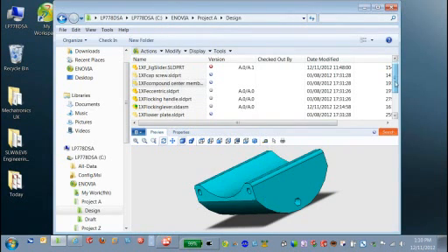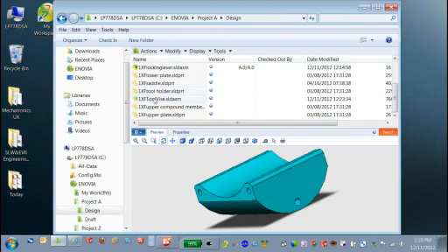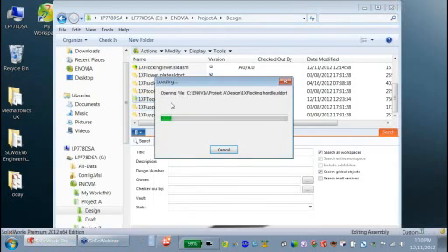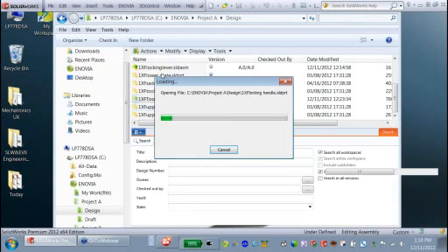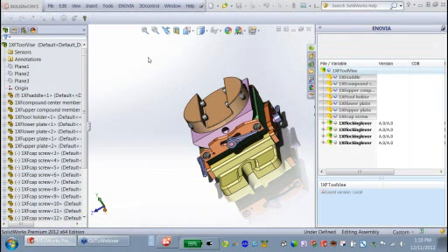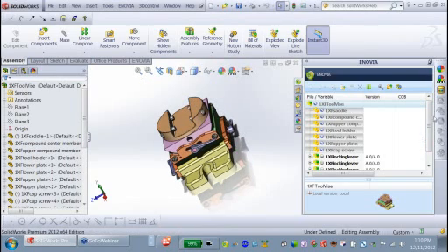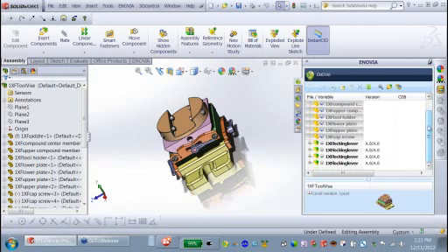Now, for this situation, what I want to do is take advantage, go right into SolidWorks here. So I want to open an existing assembly that I've already got that isn't under management yet, but it does contain some of these other components we see in the same folder that are currently managed. Here I've opened the assembly in session, and one thing you see is to the far right, there's a tab called ENOVIA, and this is the actual view or dashboard, per se, of the management system running in the background. You see here all the various parts, the hierarchy that you're familiar with in the regular feature tree to the far left.